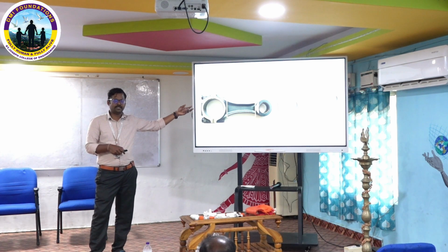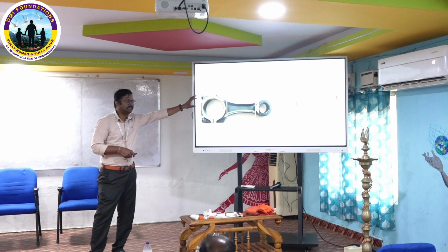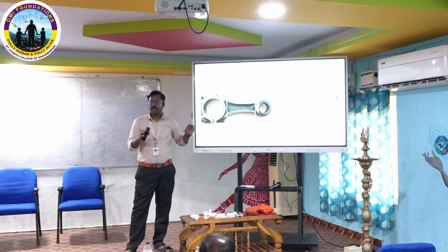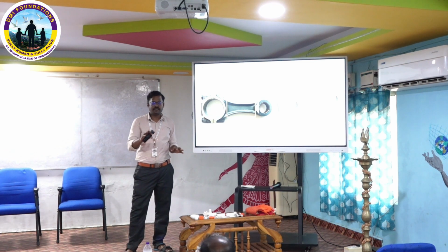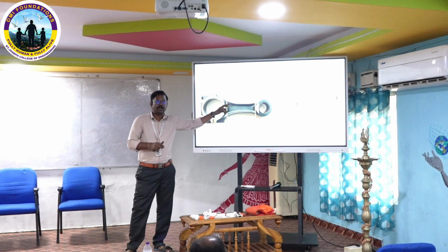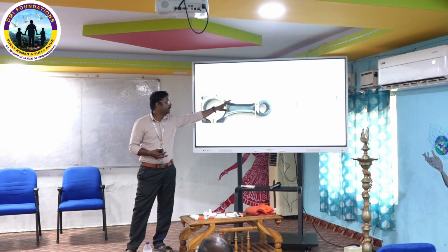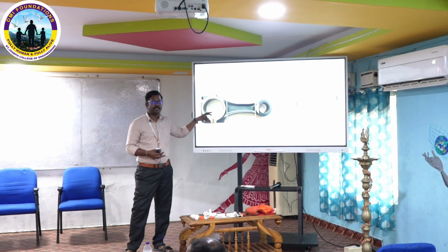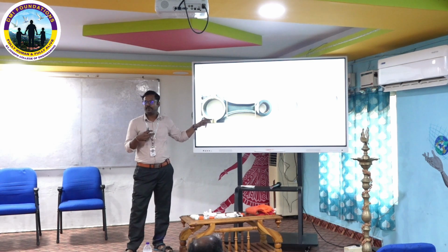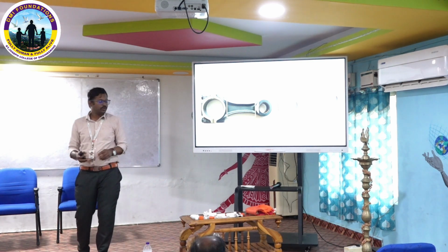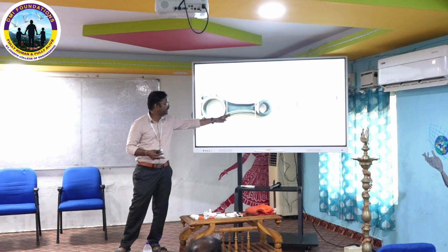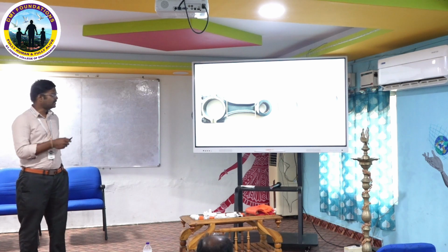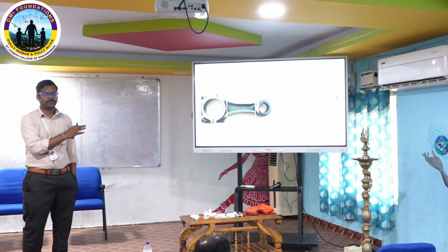In topology optimization and part consolidation also, we need to consider the design space and non-design space. Here, no load acts. The portion where stress concentration is higher, I select as the design space. Where the load directly acts or at any mating places, I consider that as a non-design space. So I take this design space, then I incorporate my lattice structure into the design space. These are the first steps of incorporation.